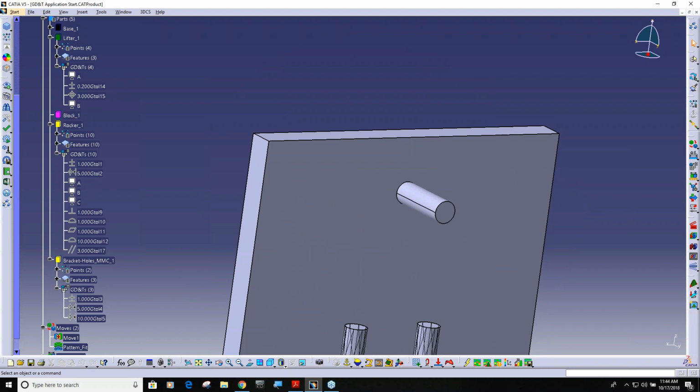We're not required to follow the order, but that's why when you add your GD&T, you are required to hit a nominal build and separate. Because that's where we look at all the GD&T and we figure out that, oh, you called it datum B and then you added perpendicularity. So we treat it correctly. That's why you have to do a nominal build first. So we scan through everything.